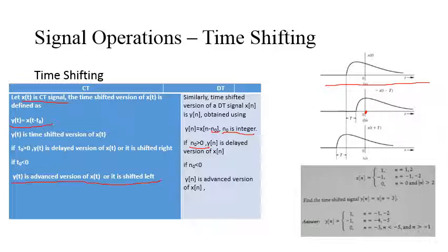So if you are shifting something towards the future, we normally say you are delaying it, right? Because it is supposed to be done now, but you are delaying it maybe for an hour or whatever amount of time, then we say it is basically delayed, right? So similarly, for example, you are supposed to do your homework now, right? But you have already done it. Then in terms of signals, you say you have shifted the signal to the left, or you say you have advanced it, right? So I hope you understand the terminology for the delay and advance, right?